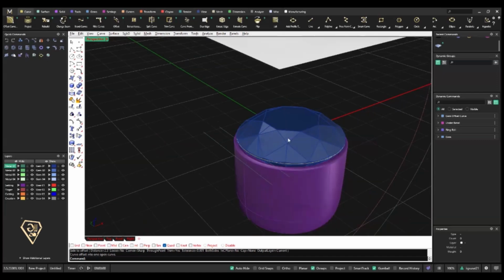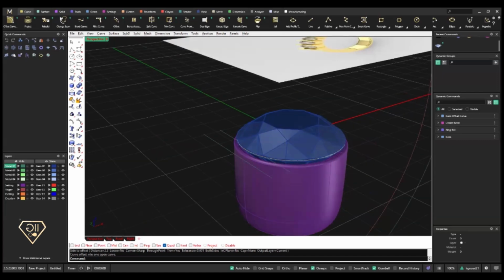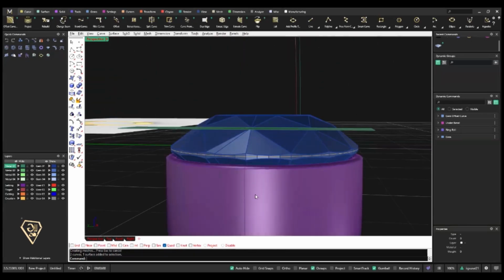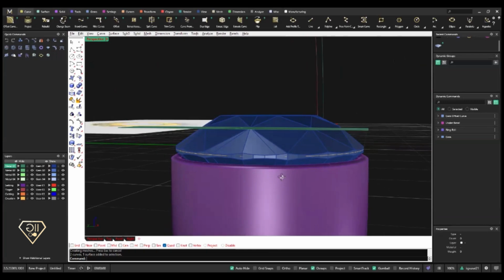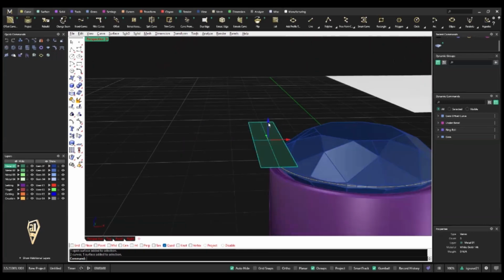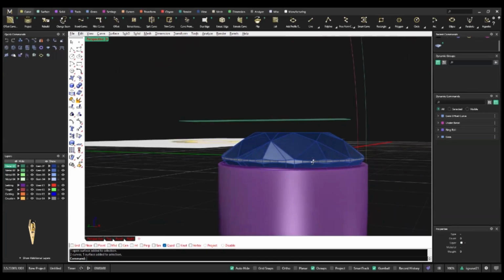So basically now this is around the girdle side. So we'll click on this thing. First let's do loft for this. Okay, so we have got a surface of this thing. We'll box select all three, and with this blue arrow, you can keep from 0.5 to 1 mm. Okay, if I do 0.5 over here, from over here we will get the whole bar at the bottom of this side. Let's try 0.5 more, so it will be total like 1 mm above this thing.